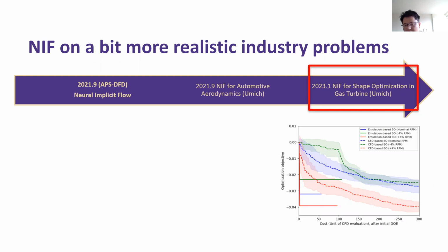You can query any pressure or drag values at those points, and I think what George did is he used Green's function to compute the surface integrals, and then used that as the output of this black box surrogate model going to the Bayesian optimization module. Then the Bayesian optimization module determines where to sample the next parameters.